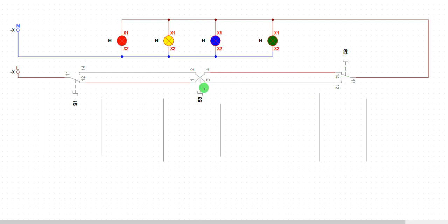Now the work of intermediate is to close, like I have this one passing by intermediate. Now work of intermediate is closing 2 and 3 and also closing 1 and 4. So let me off this light from intermediate. Look at it, I shut it down now. So 1 and 3 is closed, 2 and 4 is closed. That is closed circuit. Then if I want to use that to activate that lamp, I will now activate it. Then 1 is going to be connected to 4, 3 is going to be connected to 2.